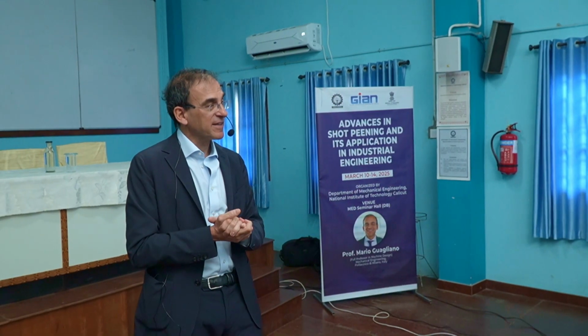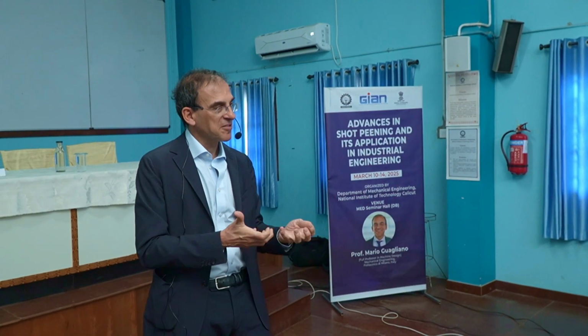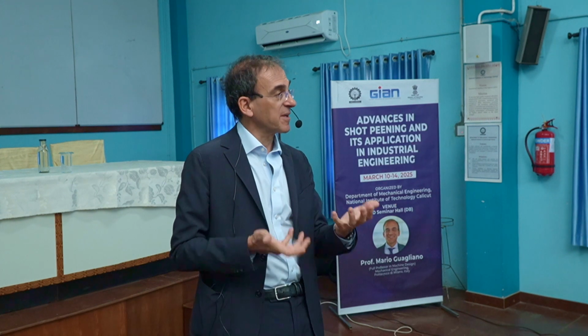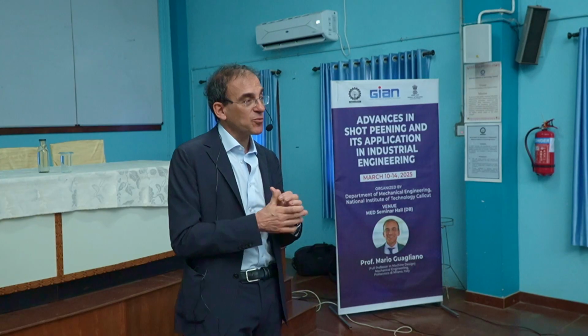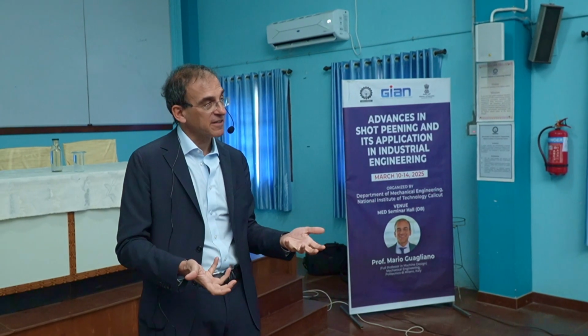This is about, now we talk about the process. We define the parameters, the general parameters that define the process: the media, the intensity, the coverage. The next step is to talk about the effect and how the effects are related to the parameter. This is the key knowledge that makes it possible to design a shot peening treatment.